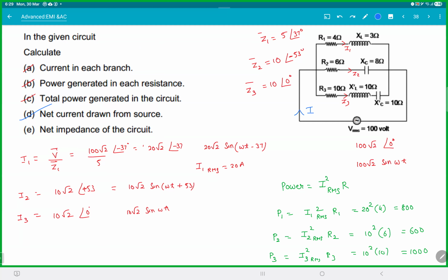Can we not use power factor for the average power in the circuit? So how do you get the phase angle, right, Prakriti? The formula would be VRMS, IRMS, cos phi. Which VRMS? This VRMS. Which IRMS? This IRMS. Which cos phi? The angle between these two.